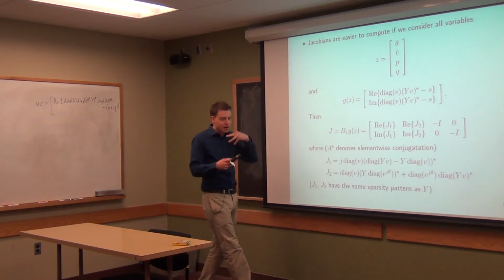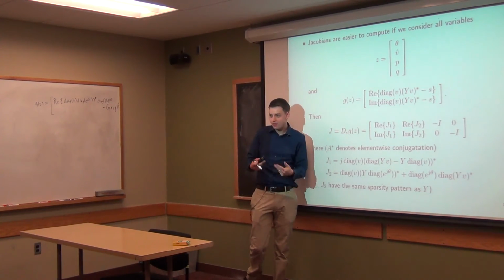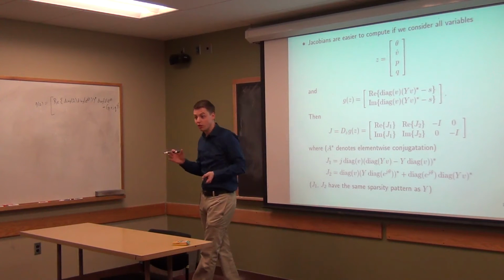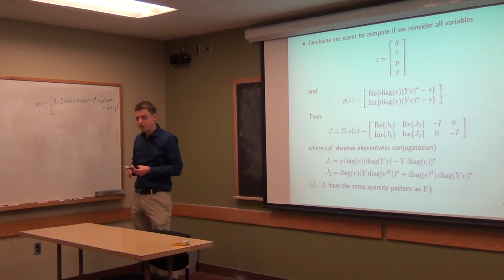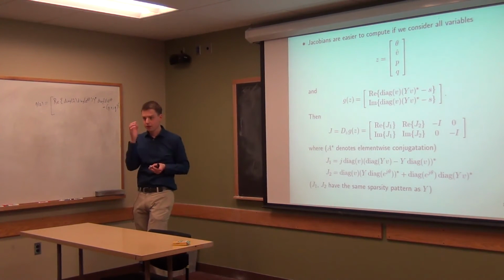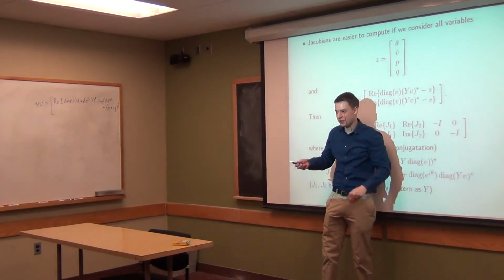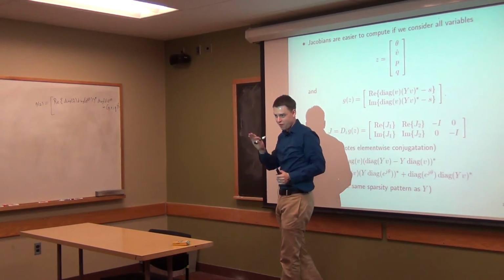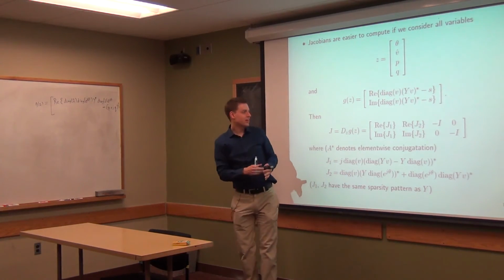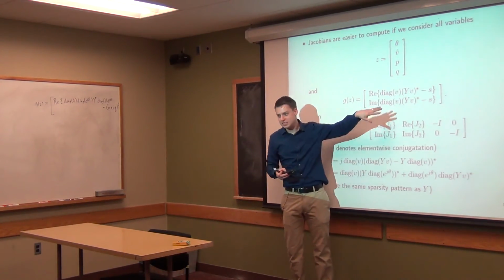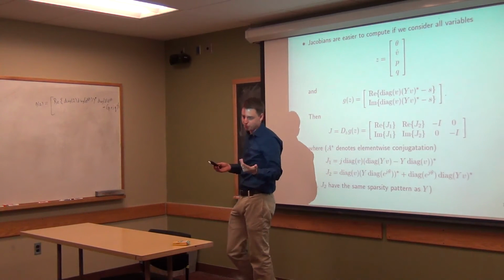But in intermediate steps, it's: how will our power flow equation change in the first order approximation if we start changing numbers a little bit? That's actually very, very useful to think about for things like perturbation analysis. When you have a solution, you want to know, if I change things, if I increase my load, what will happen? Which directions will this go in? That's very, very useful there. But in the case of intermediate steps where you're just solving this thing, these are just numbers. This is just a function.